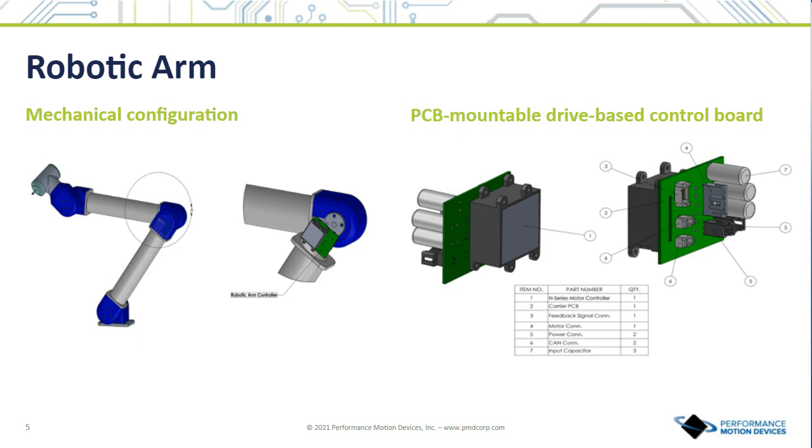So there's a lot of sophistication in these drives, and it allows you to put in a lot of user code. We've had customers that do sub-micron motion, and they put in advanced compensation tables and path planning, where they would do a certain move, a gross move, and then there would be a fine-tuned move at the end, with a lot of compensation tables based on the mechanical structure of their system. So with a smart drive like this, you're able to do a lot more than a standard drive.